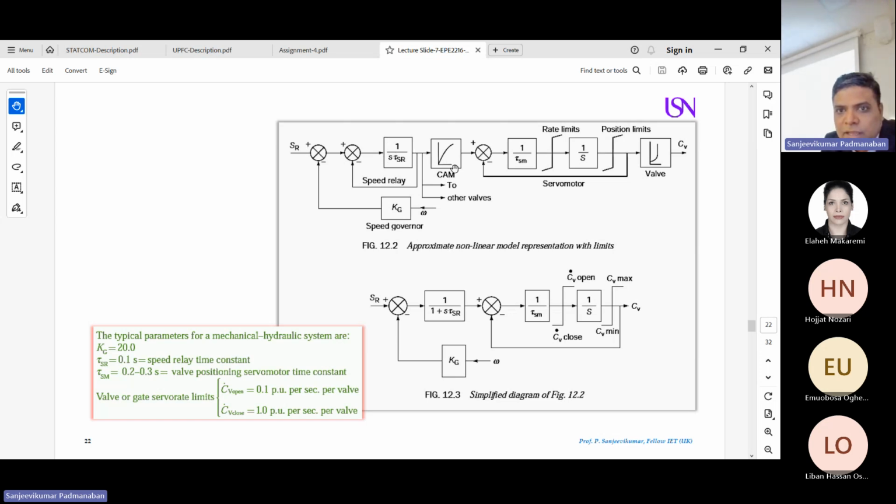From the integrator, we give it to a CAM model, which is a linearized function. In this linearized function, I want to start my speed from 0 to maximum. You see, very smooth. So here I create that from this system. Then I have a servo motor, which is my synchronous machine. This output is given, and the feedback is the position of my machine. Then again, I have an integrator, given by 1 divided by S times the time constant of the machine.